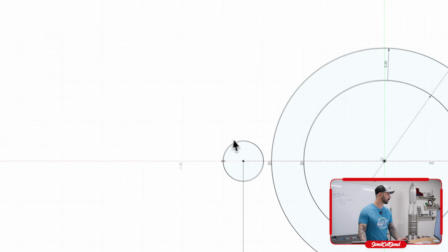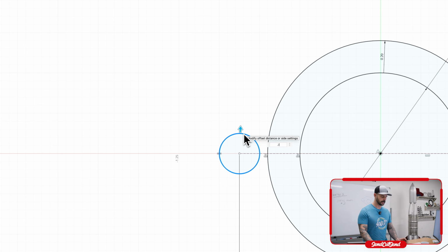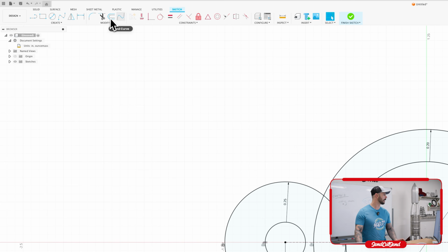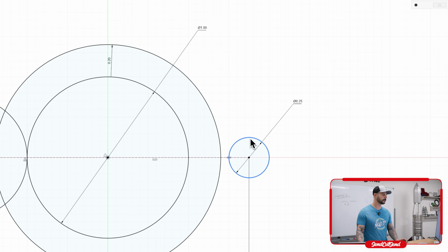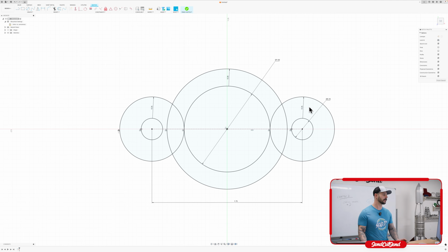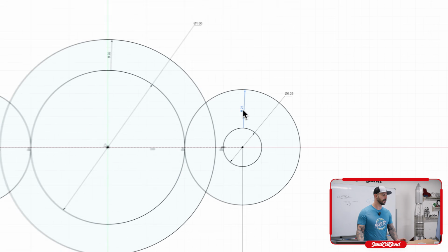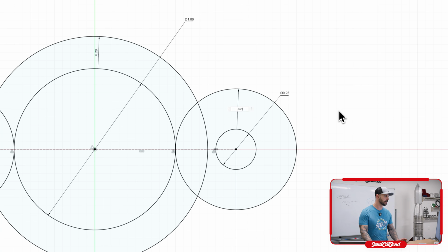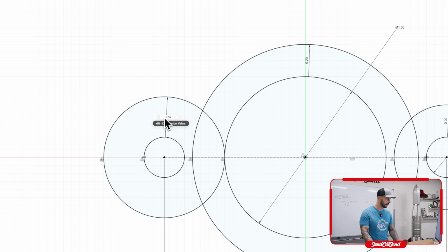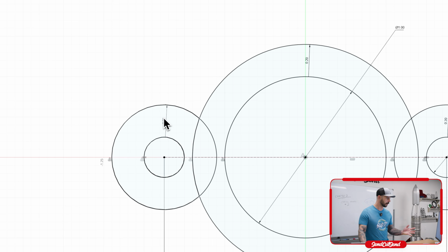We're going to do the same thing around our outside holes here. We're going to add the 250, and one last one on this other hole. So we're just adding those offsets again at 250 thousandths of an inch. And you can see that dimension comes through here. We can always change that to 200 if we want. We can change this one back to 200 as well. So all that's kind of working with it.